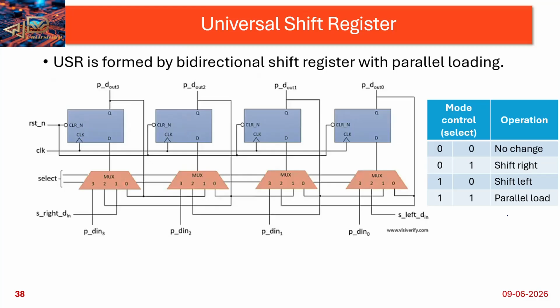Okay, just see. So this is the circuit diagram, logic diagram here. Just check this multiplexer. So here I am taking a 4 by 1 mux. In this 4 by 1 mux, 4 inputs I am taking, and then 2 select lines. Based on these 2 select lines, that is S0 and S1, we are getting the output, that is data is loaded into the D flip flop.